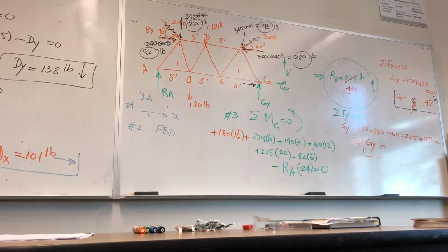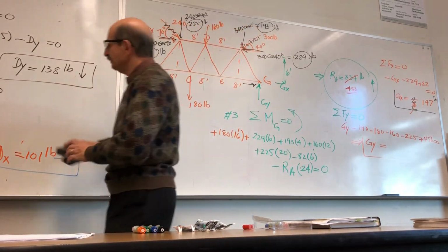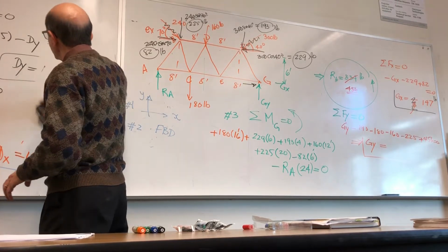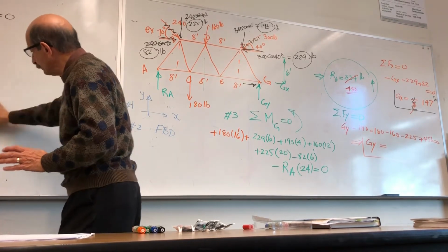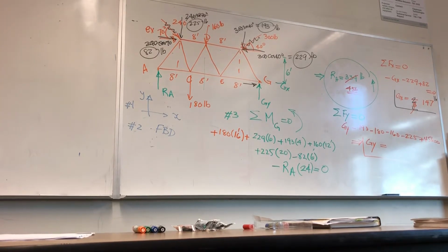Okay, so I was hoping that we'll still have 3 minutes. The part that I want to know how to do was how to find the line of action. Yeah, it's the type of problem we did, where you need to move the forces to a point that you don't know where it is, say X from A, right? Then, since the summation of all the moments has to be 0, you take the summation of moments about that point, you find X. You remember we did a problem like that? It's exactly like moment over the force.